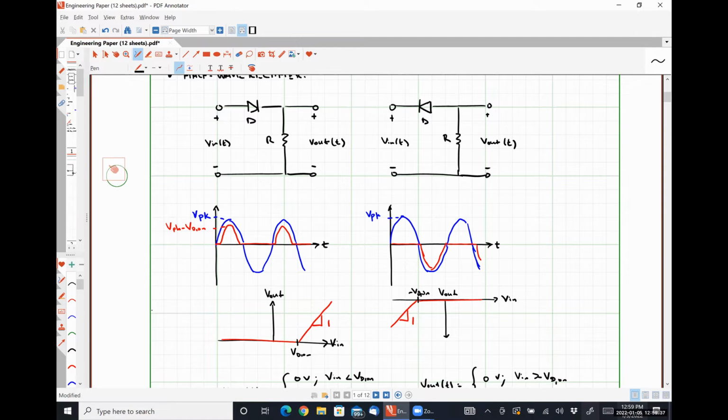Slightly greater than, So I would argue that it wouldn't be slightly greater than that. It would be whenever V out is at its maximum, all of that V out is being applied across our load RL. That's going to be our maximum diode current. Does that make sense? Oh, I thought you were asking what the diode is rated for. Oh, no. Okay, yeah, so the diode should be rated for slightly greater than that.